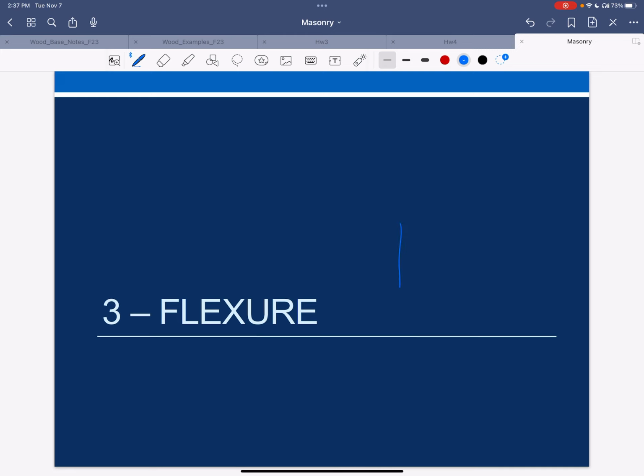So if I just look at concrete by itself, and I know it goes like this, this is a stress strain curve, or you can call this little f. And when I do this for concrete design, this is essentially at ultimate, and I turn that into a Whitney stress block. That's how I get this thing. This is essentially the concrete stress at ultimate, and I have a crushing strain, and I have some slides on this. Now I'm only in what's fairly much a linear elastic region.